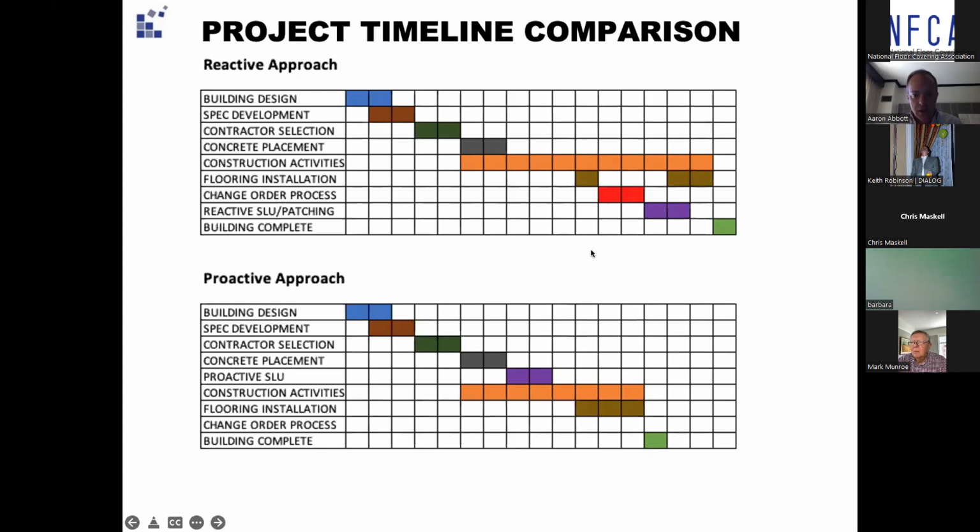Exactly. I think the construction industry just assumes the floor cover will carry the cost to fix the subfloor because it's their subfloor. They know what they need, but it's actually not in the trade scope of work for a floor cover to take on any work beyond the 3/16 over 10 feet, or whatever the manufacturer of the floor cover calls for in flatness. So they won't carry the costs unless there's a pre-agreed contract where they say, yes, we will bring your Division 3 finished product up to floor cover standards. We'll pay for that. Then there's an agreement in place, money allocated, and off they go.